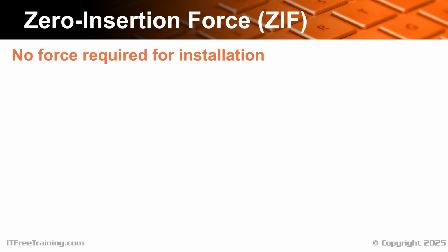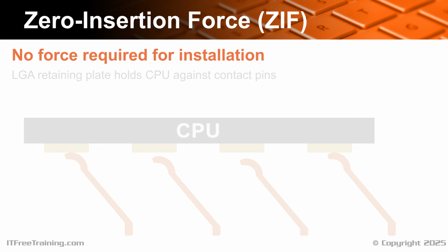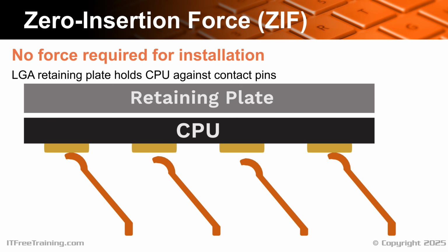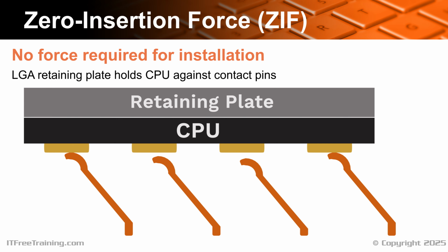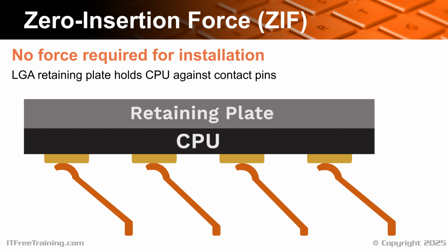When working with electronics, you'll hear the term zero insertion force or ZIF. ZIF in electronics means zero force is required when putting in components or cables. CPUs are well known for being ZIF sockets, but it also applies to cables that don't require any force. Usually these cables are ribbon cables located on the circuit board. If it requires force, it's not a ZIF socket. In the case of LGA, the retaining plate holds the CPU in place and thus holds it against the contact pins, making sure there's a good connection.